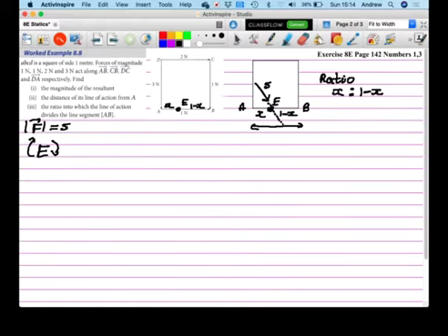So working off this diagram here, let's look at the force along AB. Because AB passes through the centre point, it means its line of action has a distance 0 from E. So therefore I've got 1 on a distance 0. So that's the AB taken care of.